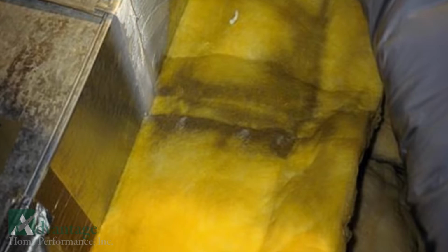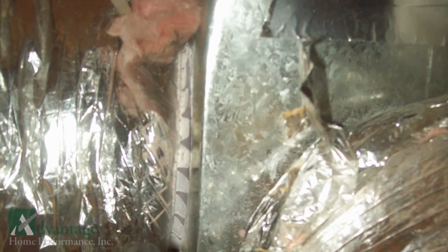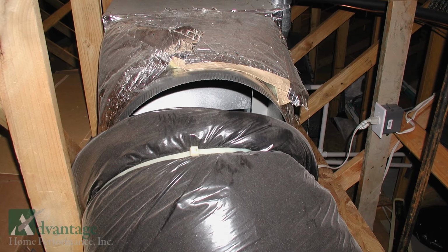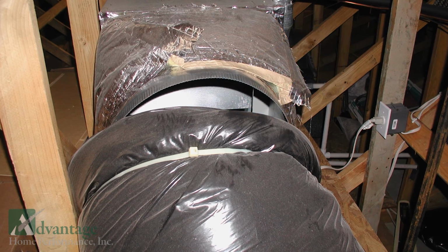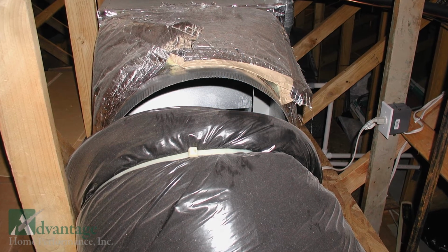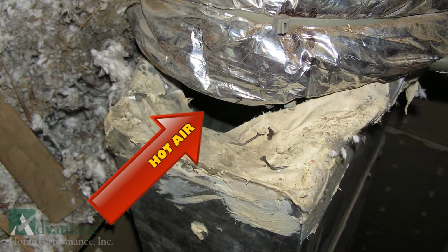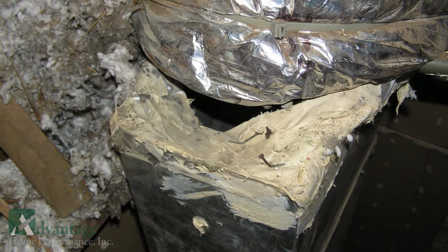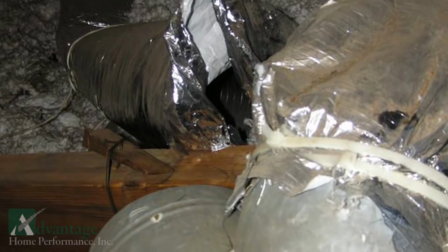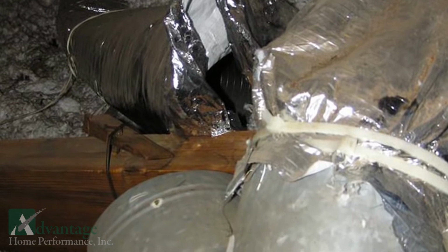We see small duct leaks like this in almost every system we test. The duct leaks only get larger and larger. Duct leakage contributes significantly to high utility bills, dust accumulation, and indoor air quality problems. When your air conditioner is running, a return duct leak will suck hot and dusty air straight out of your attic and then distribute it into your home. This disconnected supply duct is cooling the attic in the summer and heating it in the winter.